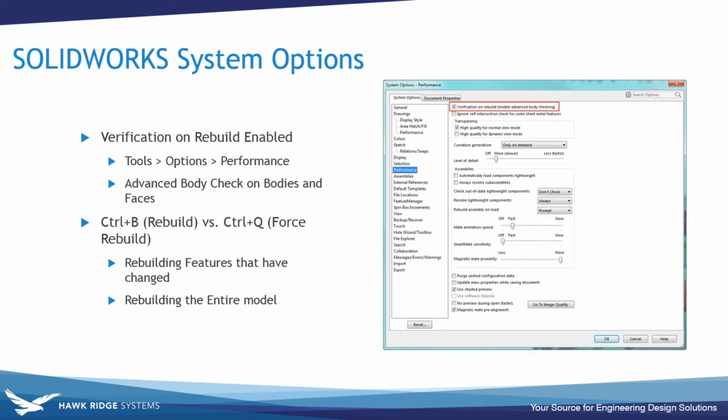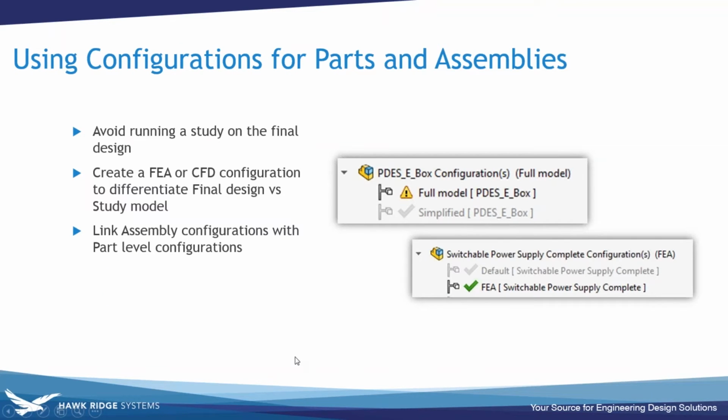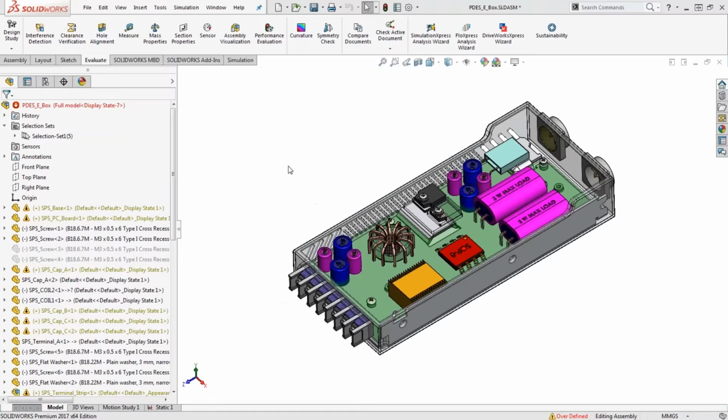Right? So eventually, you want to clean up those issues as far as a mate or any references there. The cleaner the model is, the easier time the simulation solver is going to have. Right? So definitely make sure that option's on. Nowadays, with our laptops, the performance is not really going to be an issue. Of course, if you're dealing with really large assemblies, you may have to consider differently, but at the end of the day, I personally recommend always having that option on. Okay.